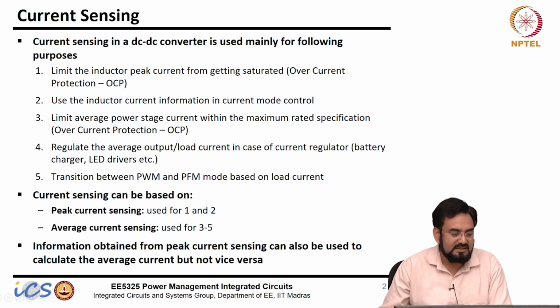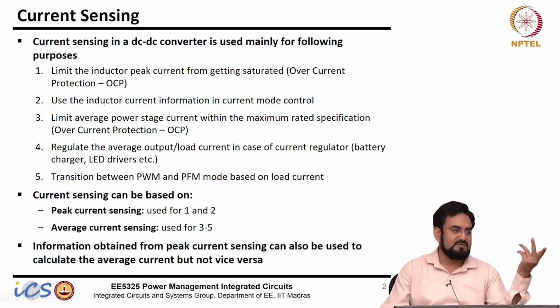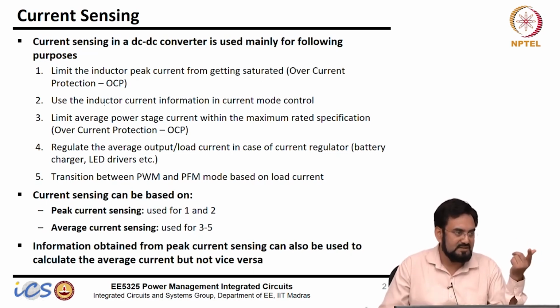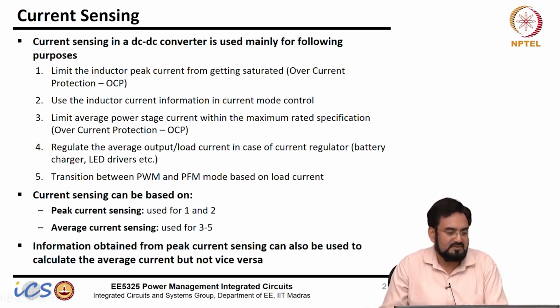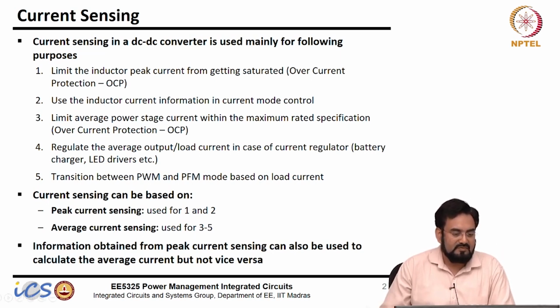But in the case of a switching regulator, we have an inductor also. So we have to protect the inductor as well from getting saturated. We need to limit the inductor peak current from getting saturated, and we call it overcurrent protection, OCP.